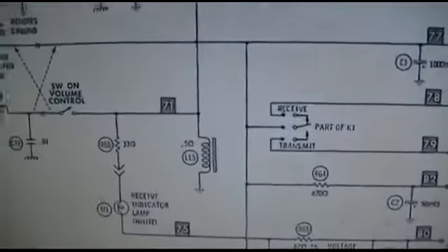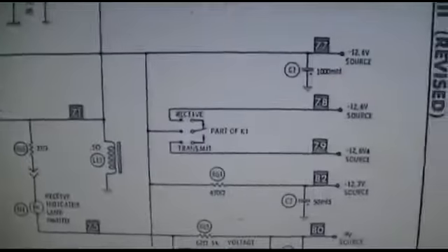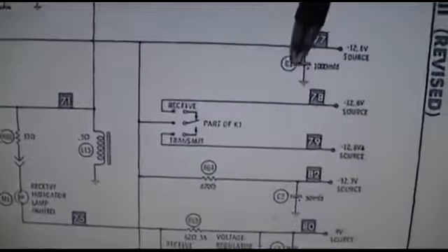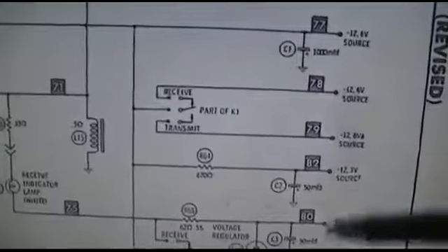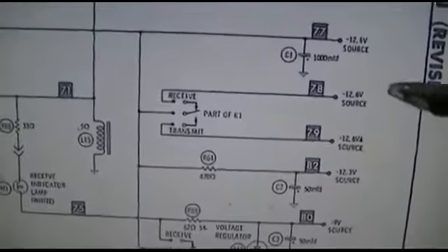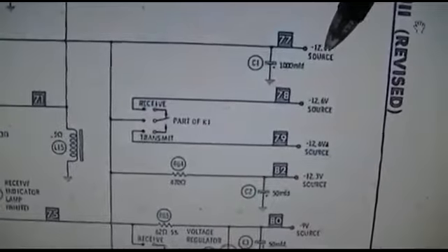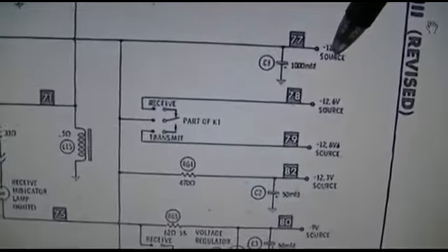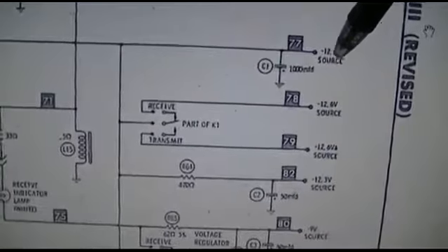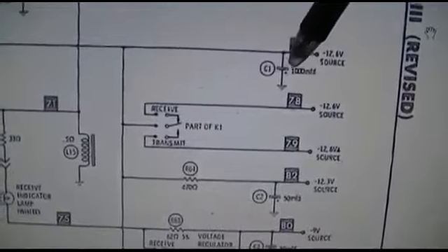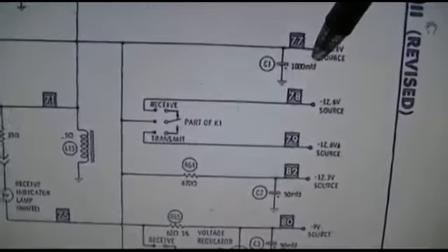Right, so this is kind of what I was talking about, the power supply. You have the power coming in here, and then this is where it branches off here. So you can see whatever this connects to would be your direct feeds that would most likely cause a short. And of course there's the capacitor right there that was causing the problem.